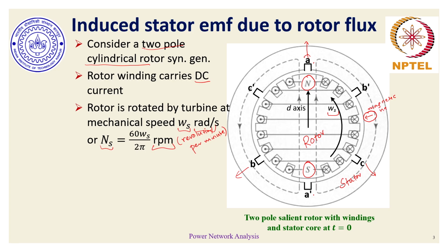So if this magnetic needle aligns with the position of the rotor, where the north pole is just close to this needle and the south pole is opposite of this north pole, probably in that situation this magnetic needle will have the maximum deviation, whereas in the position where the north pole and the south pole are in a perpendicular direction to the current needle position, let's say north is here and south is here, and this angle here is 90 degrees.